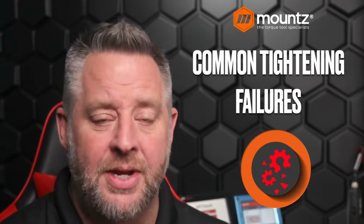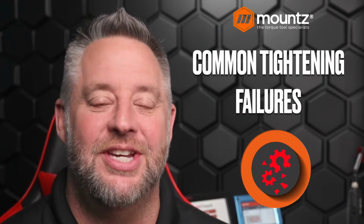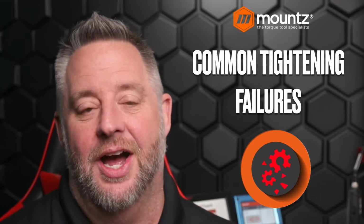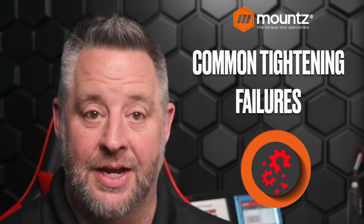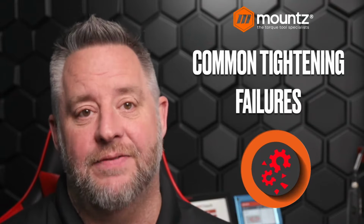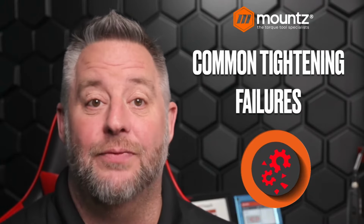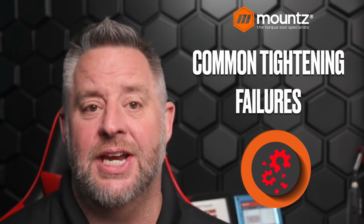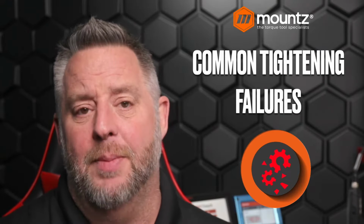Some of the common tightening failures that we typically see are fasteners that may be under torqued, not providing enough clamp load that we need for the parts to remain intact. Any type of vibration or shock can cause that fastener to fail even more. The opposite of that would be if we're over torquing a particular fastener. And this can certainly bring our fastener to its yield point, meaning that it's stretched extremely far.